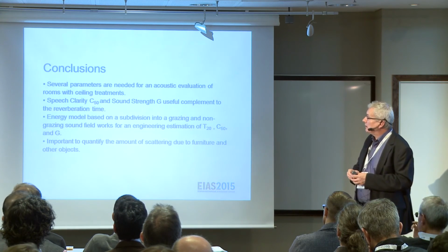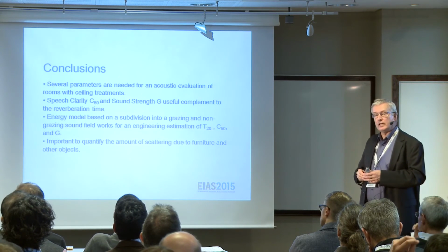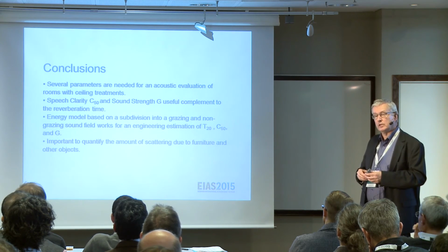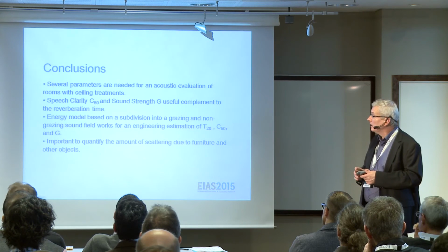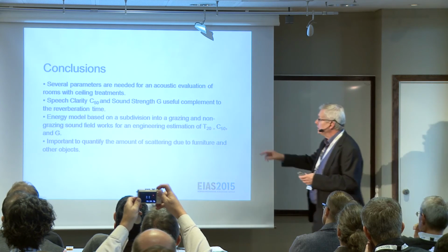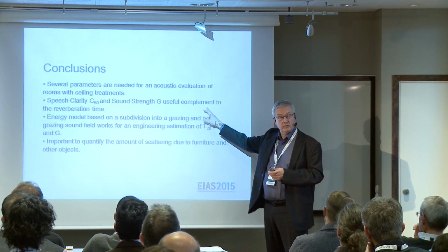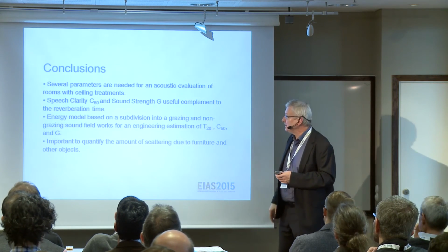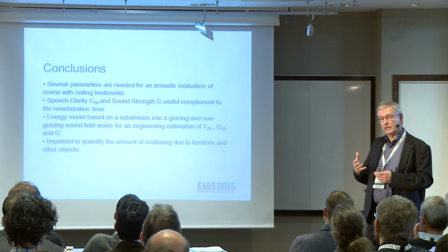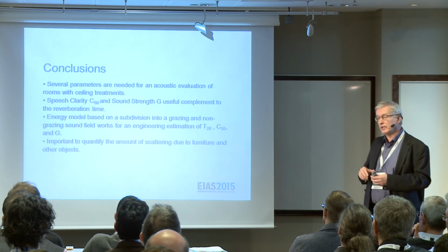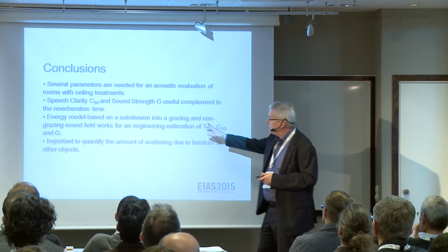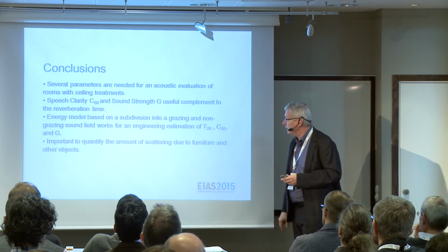So the conclusion is that I think it's quite clear that we really need more parameters than the reverberation time to evaluate acoustics in rooms like classrooms, offices, and this type of room with ceiling treatment. I think speech clarity and sound strength seem to work quite well, and we can estimate them as well. But of course, I think the main importance is that we measure at least parameters that are related to speech intelligibility or are related to the noise levels.